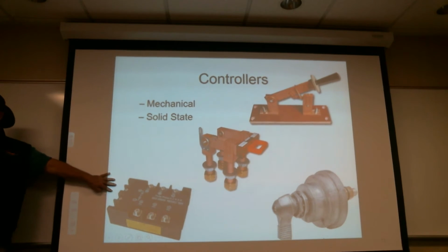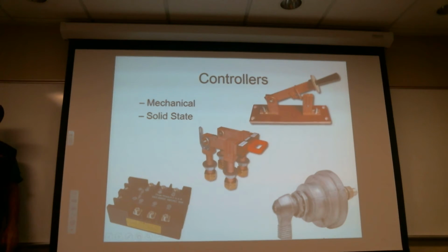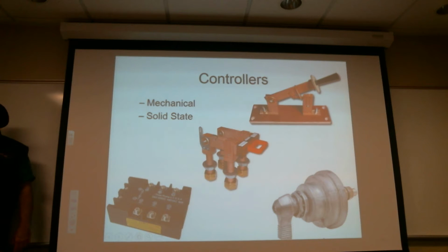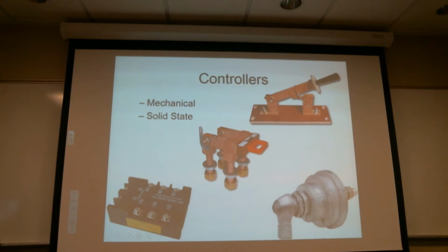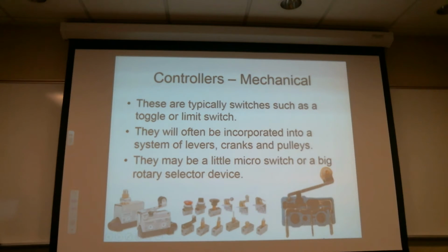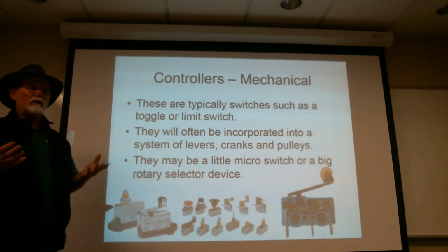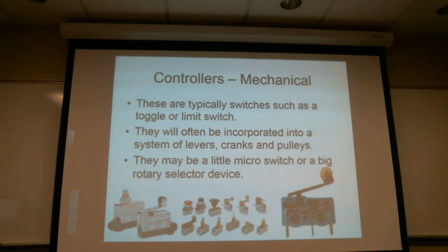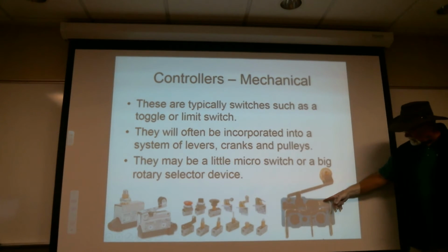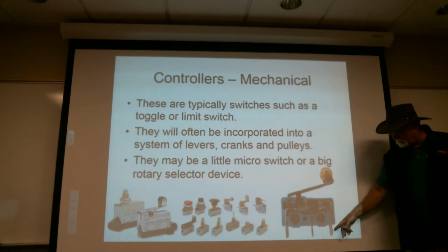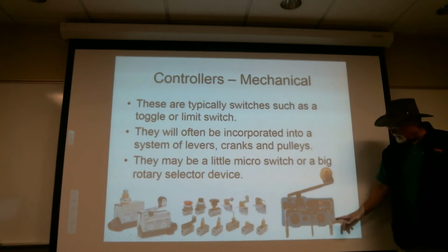So what's controlling this? Well, maybe the little pressure gauge and the little computer in the compressor that says, uh-oh, the air pressure dropped, turn the compressor on. All right. So switches are used in basically two ways, and there are other derivations, but the predominant uses are as a human interface device to turn something on or off, or as a sensor. We often call it a limit switch, but in truth what it's really doing is position sensing. Something comes up and goes whack, says okay, we're here, and the switch moves from normally closed to the other state.